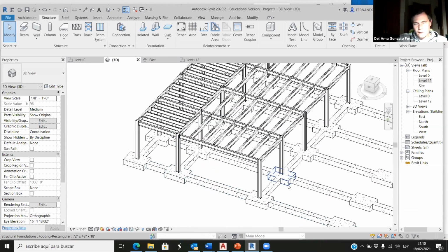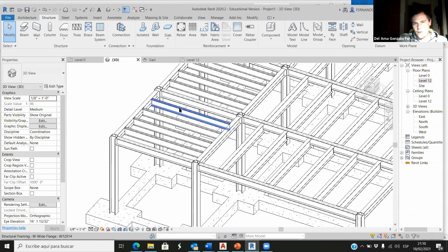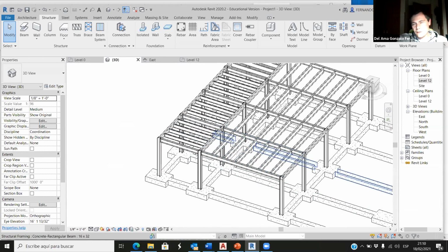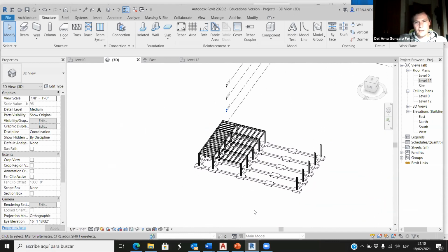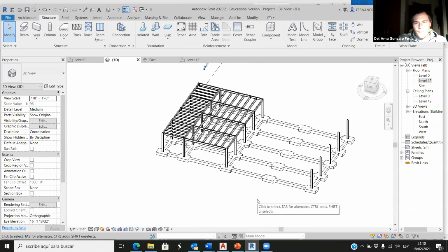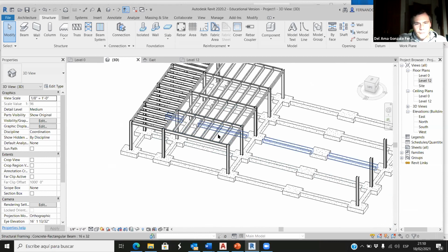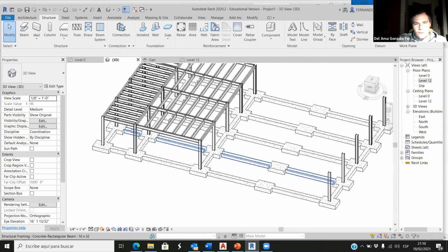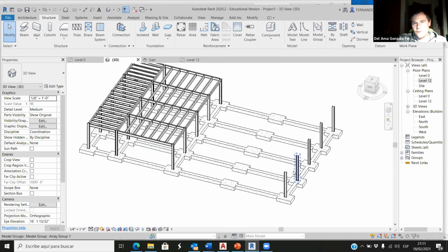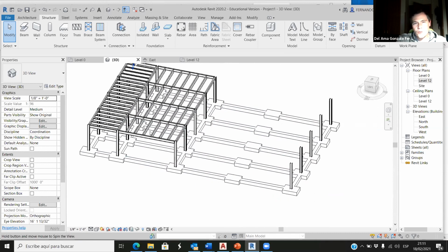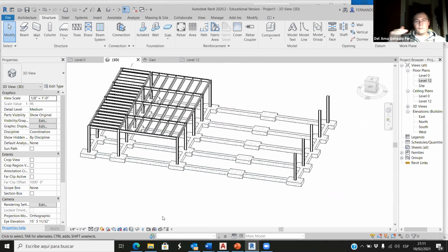So we have footings, columns, a short span with a beam system, and another frame with different spans. The beam system should be in the short direction. So it looks like a building now. But what do we want now? Those are the dressing rooms or the restrooms or other spaces, and here we have the court. For the court we need to make the structure higher, because 12 feet is good for a dressing room, but if we want a basketball court, it has to be higher.